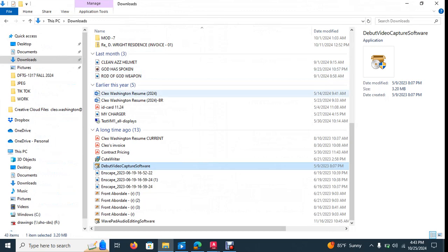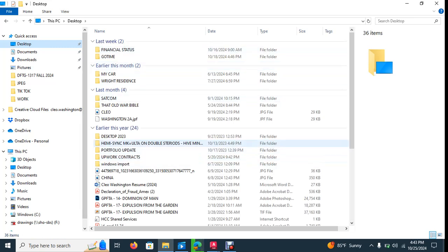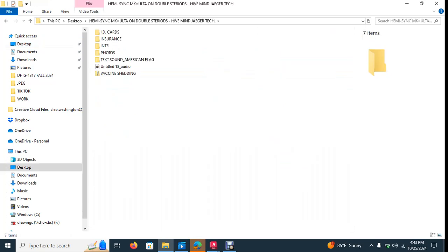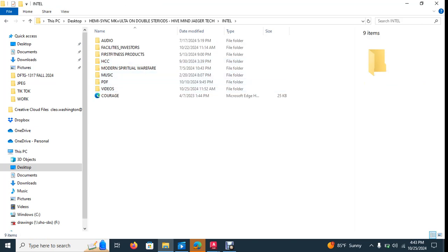All right, now let's go back and let's go ahead and take it and put it in our project folder. By the way, if you guys are getting hung up on the X-referencing, please let me know. The key to it is all the drawings that you're X-referencing, you have to make sure that you're putting that drawing in the same drawing folder. So if you're X-referencing files and you're finding them going missing, it's because they all have to be packaged in one location inside of one folder, okay? So I just wanted to point that out because I don't think I explained that in the video properly.